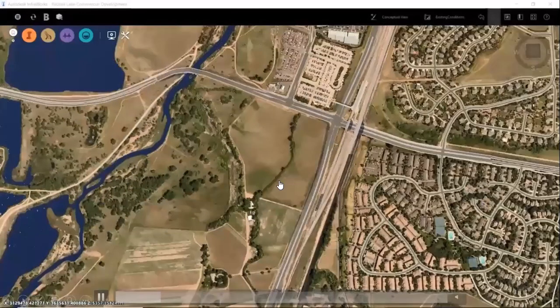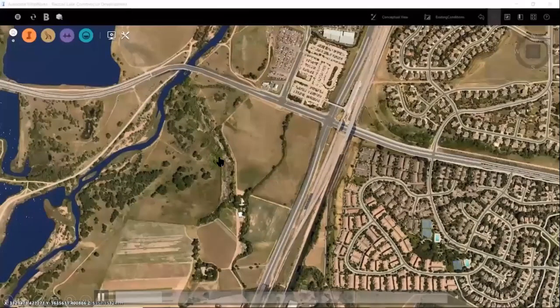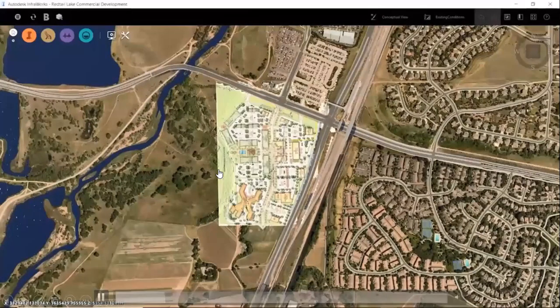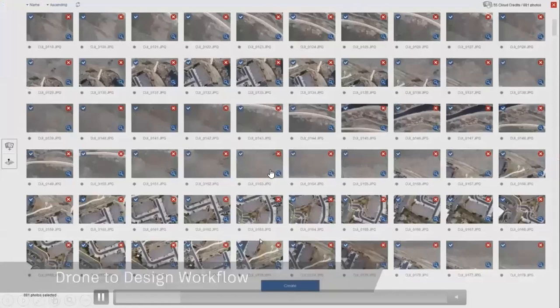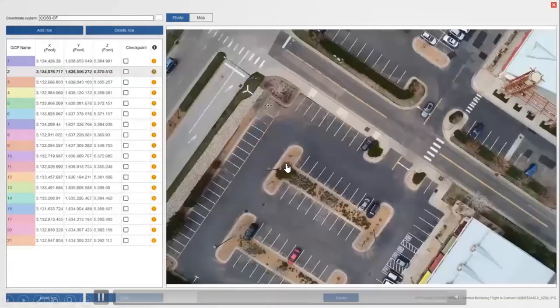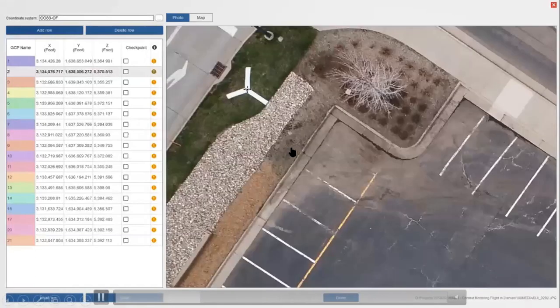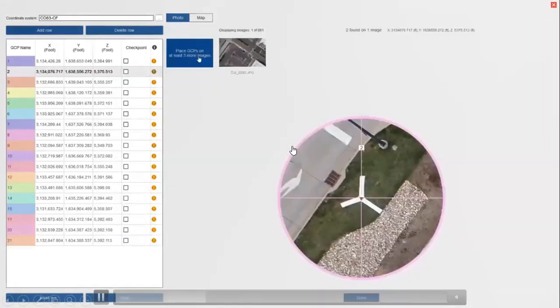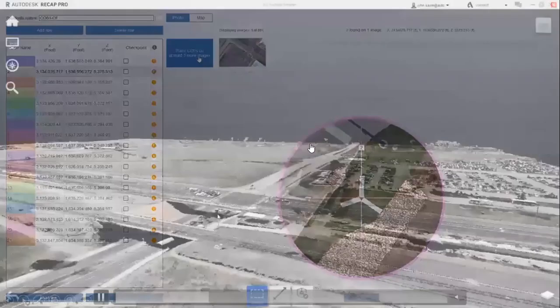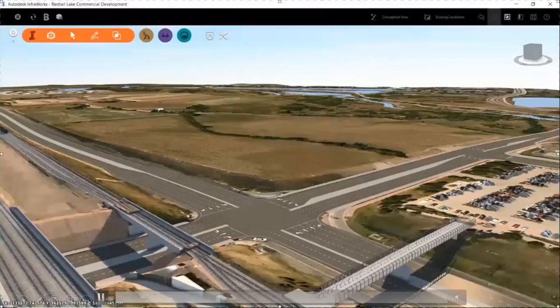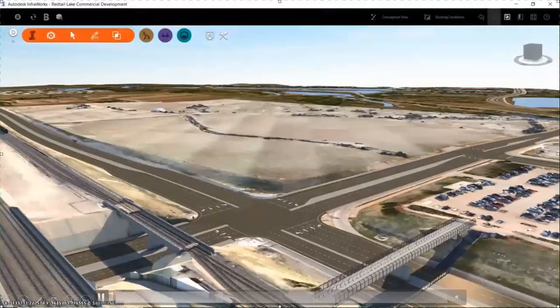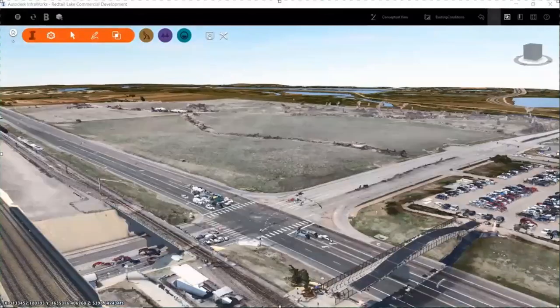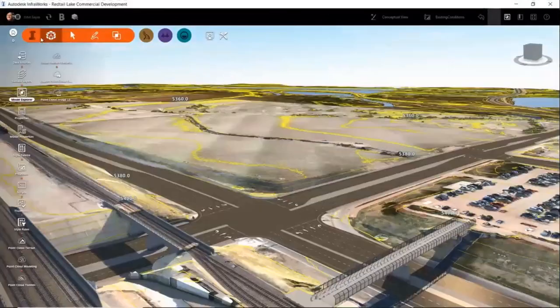Notice that now this is just a feature of importing your land terrain data, and this now utilizes Autodesk Recap, and you can also import your point cloud data for the existing conditions. You should be able to switch within views. You should be able to visualize your contours.